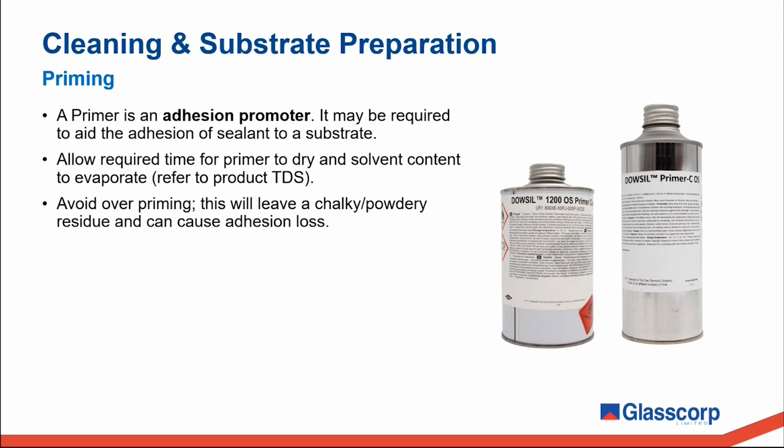Finally, it's important that you don't overprime. So when you see a chalky, powdery residue left on the surface, that may be a sign that too much primer has been applied, or that the primer has expired and is no longer suitable for use. In either case, there is a risk that this will inhibit adhesion and not help it.